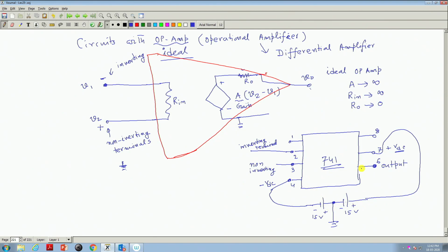This is how we identify these terminals. So, an operational amplifier is nothing but a differential amplifier. It amplifies the difference of these two signals, that is V2 minus V1. V2 you apply with respect to the ground. Where is that ground? No point in this chip. Ground is what you have created while giving supply to this op amp. We will not go deep into how it is realized with the help of transistors; this is outside the scope of this one.